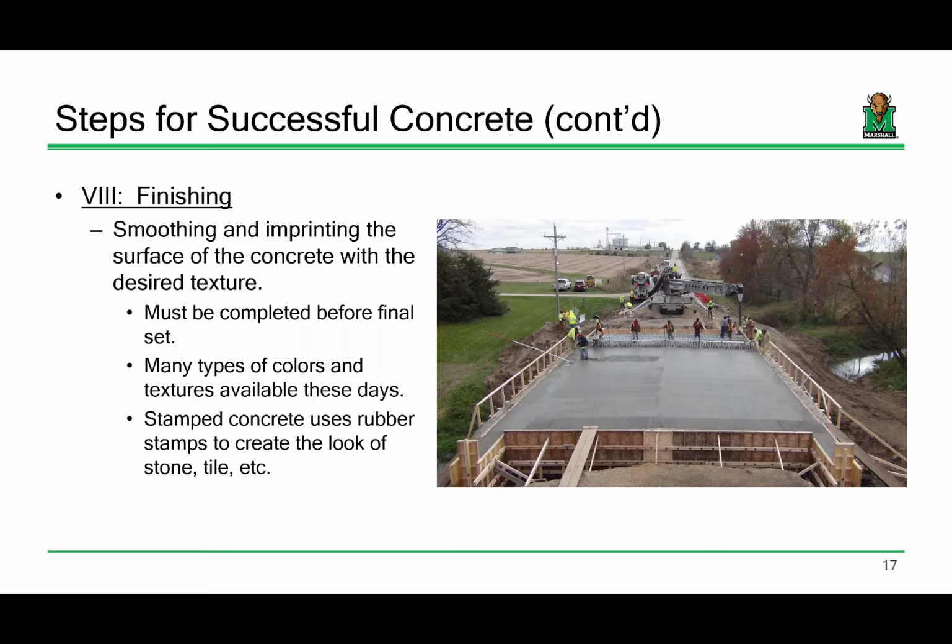It has a texture to it. For example, if you look at sidewalk placements, when they place a sidewalk, they will smooth out the surface, but then they also have essentially like a concrete broom that they will drag across the front that leaves sort of a ridgy texture on the top so that you don't slip. You know, the sidewalk isn't slick when you walk across it, okay?